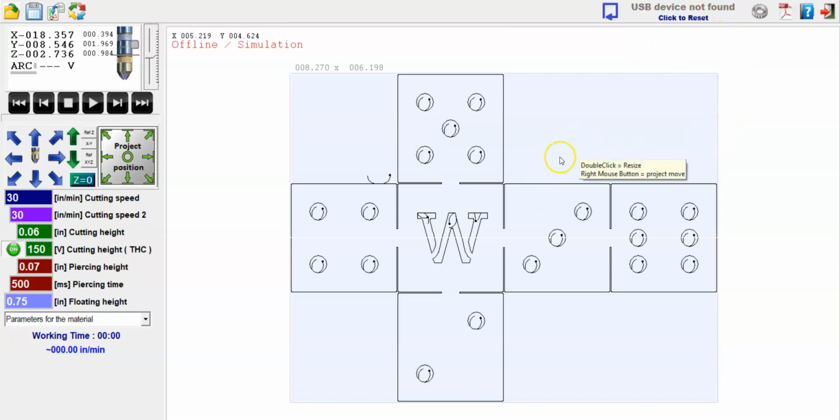One of the first things that you're going to do when you install the MyPlasm CNC system on your computer is go onto the customer portal and download the MyPlasm configuration file. This is going to be a zip file that is downloadable off the portal, and you'll be installing it into your MyPlasm system. Now we're using version 1.0.7a, and as these videos go on, we might see other updates in this software as they create new iterations. So keep that in mind. We'll be sending out updates to this video as time goes on.